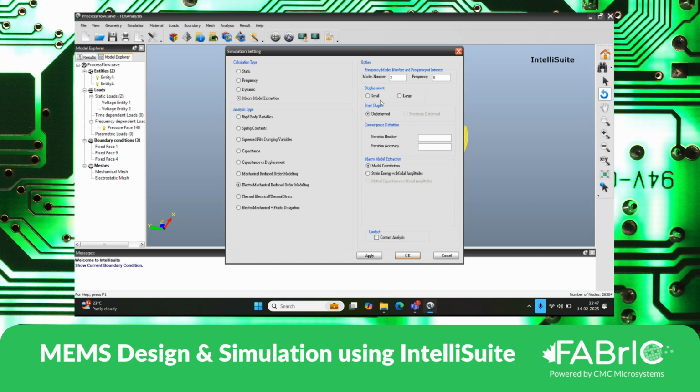And in the model contribution, we either select small or we select large displacement. If the input load is pure electrostatic force, then we use small displacement analysis. In case there are loads which are linked to mechanical like pressure, acceleration, then we use large displacement analysis. Okay, either of the two.